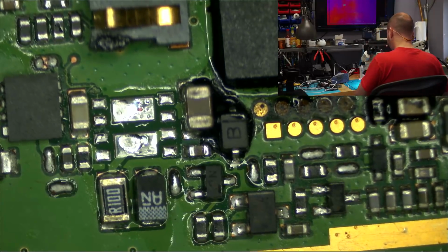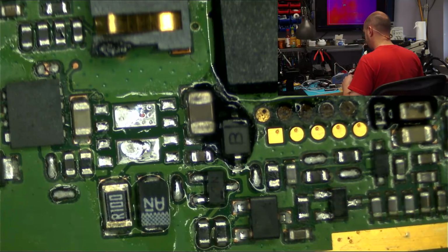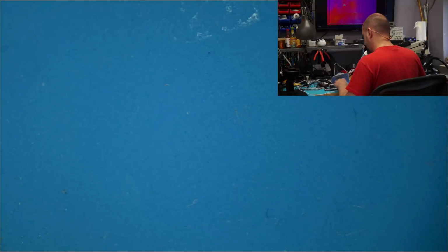Okay. Now let's see what this board takes when we plug it in. Put it back in a case. Think we could be lucky and that MOSFET's not needed for it to boot? I doubt it. It could just be for the camera flash or something. That'd be awesome if it is. Okay, let's plug it back in and see what my USB amp meter tells me it's drawing. 0 amps. So that's probably the main power MOSFET because it's not taking the 20 milliamps to boot.